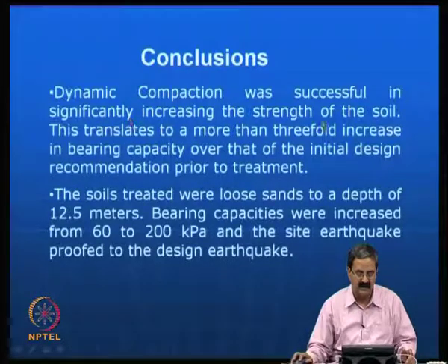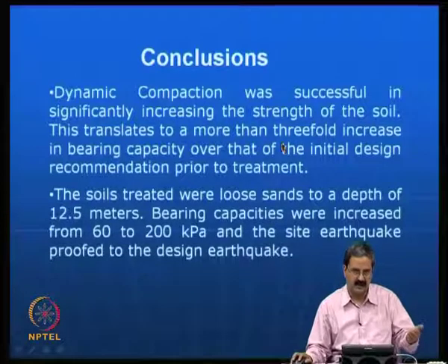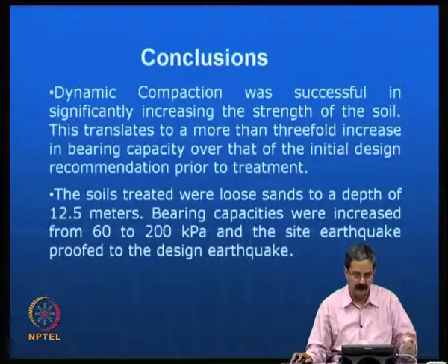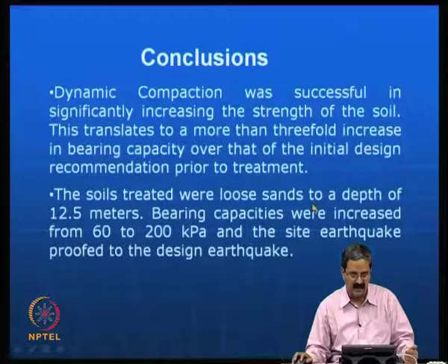in significantly increasing the strength of the soil, and this translates to a more than threefold increase in bearing capacity, like what we thought was 60 kPa, now you got 200 kPa. So, that was quite good. Then the soils were treated, loose sands up to a depth of about 12.5 meters, and bearing capacity increased to whatever we wanted, and also the earthquake resistant design was possible.